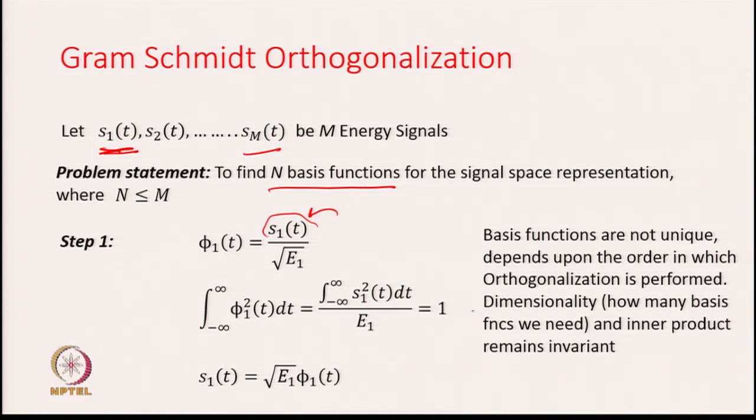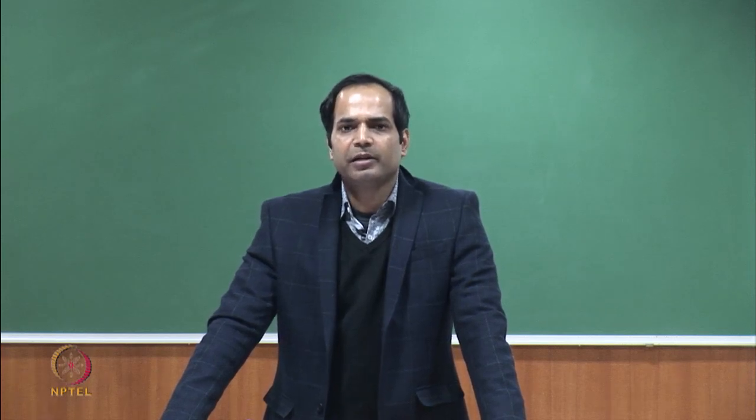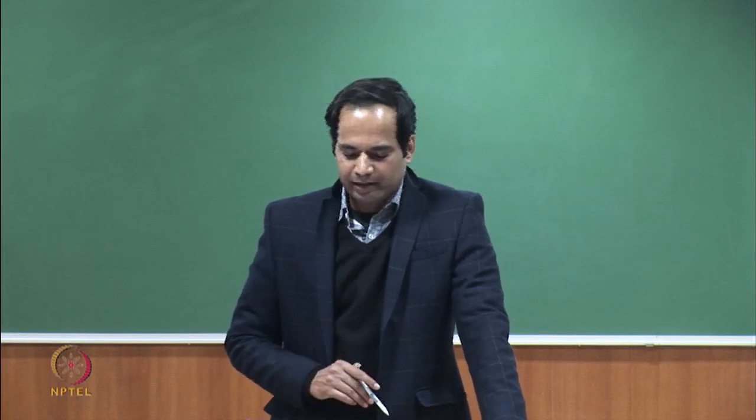However, the dimensionality, that means how many basis functions we need for the signal space representation, would not change. It would be invariant to the order in which we are carrying out this orthogonalization procedure. So, dimensionality is invariant to the order, and also the inner product between the two signals would be independent of the order in which you carry out this orthogonalization procedure. And this is really what is important: the dimensionality and the inner product between the two signals should remain invariant. Okay. So, let us get started.